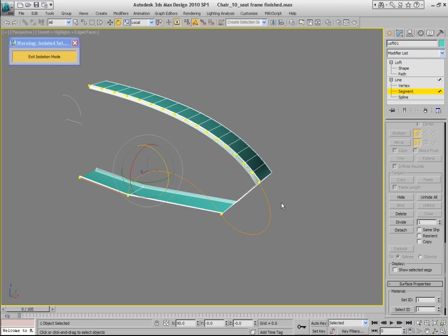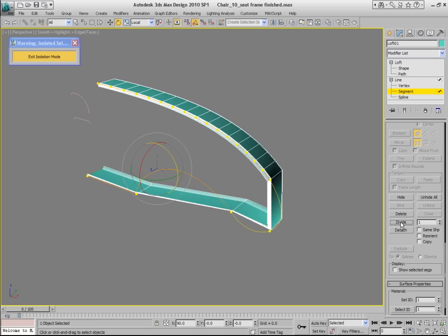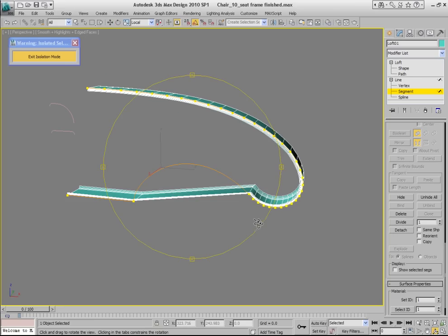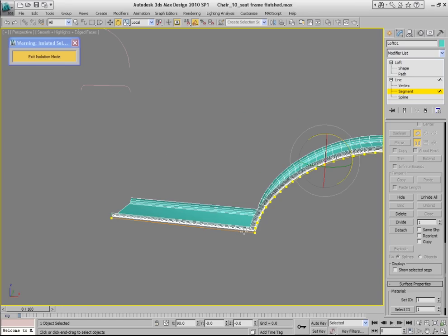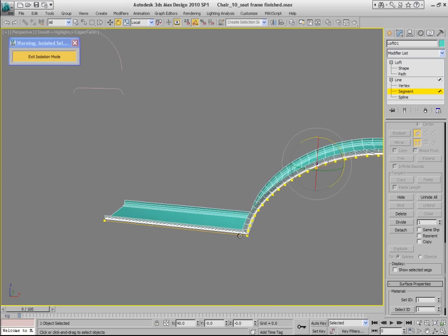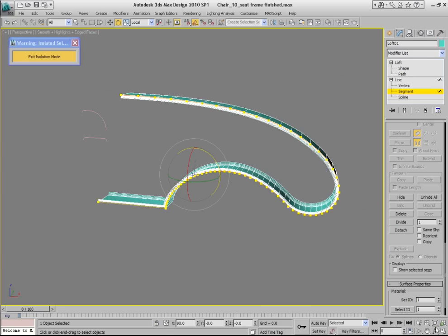So continue doing this for all the other curved segments. Just do the same thing. Just click it once, twice, or more times. And this last curved segment at the bottom. All right, so that looks great. You don't need to do anything to the straight line because it's just a straight line. You don't need to have any number of segments dividing it. Okay, so that looks great.